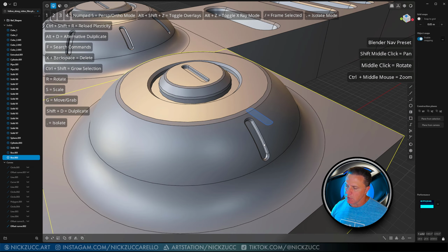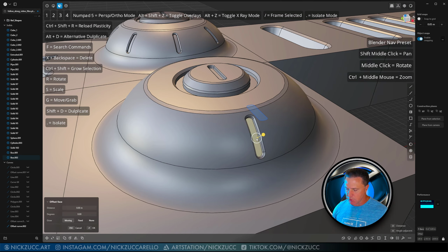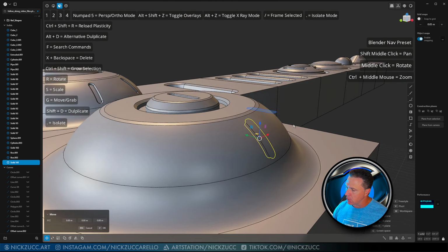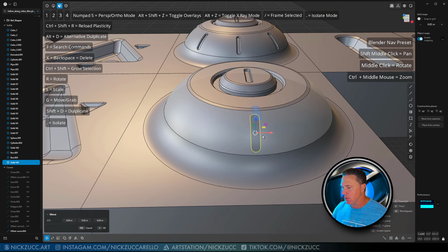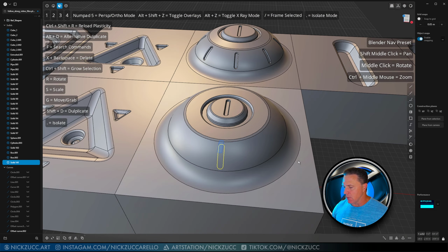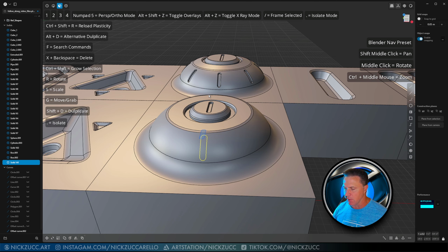This is where I wasn't sure how this is going to be handled by the program. So I'm going to tap 3, and we're going to hold down Control Shift and then the plus to grow our selection out. Now if we hit Alt D, that'll duplicate special, and look at that, it filled it in for us. Okay, pretty cool. I'm going to hit OK. And the reason I wanted to do that is because other than making a bunch of curves, we could take this curve and use the radial array, and we could imprint all these curves on here and do all the work, but I didn't want to have to sit there and fillet all of these things.